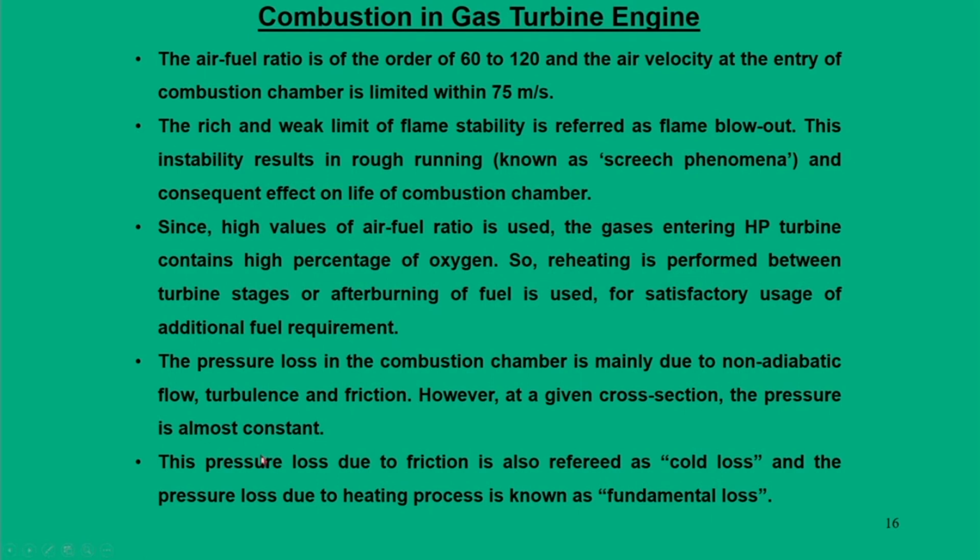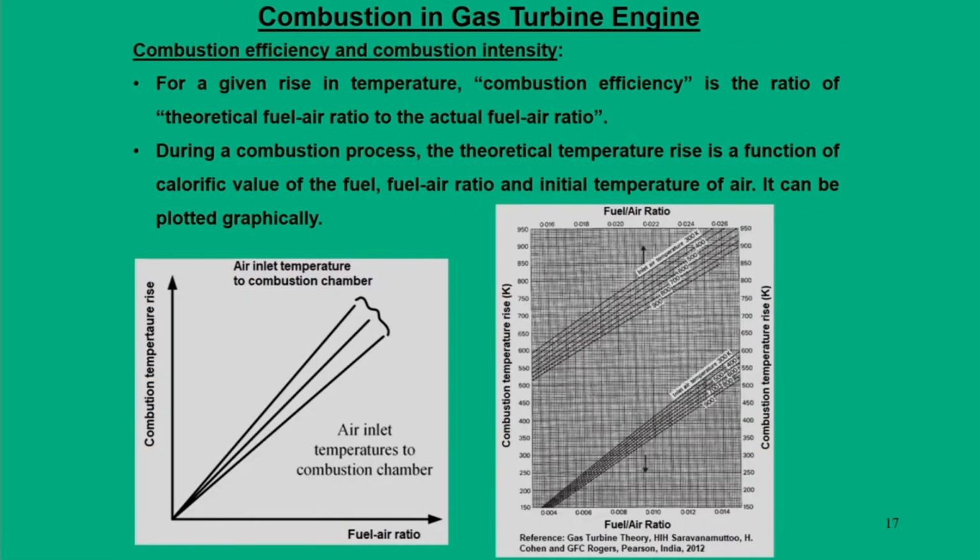In the combustion chamber, the pressure loss due to friction is called the cold loss, and the pressure loss that happens due to the heating process we call the fundamental loss. More or less, pressure loss is inevitable.